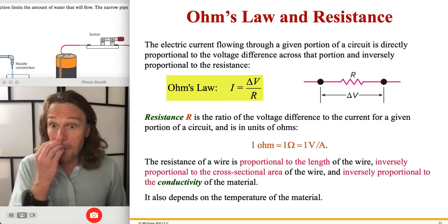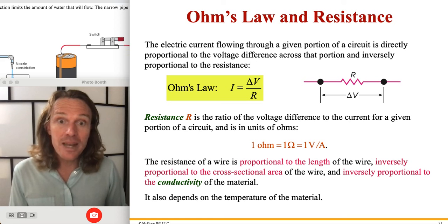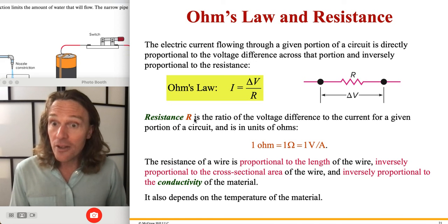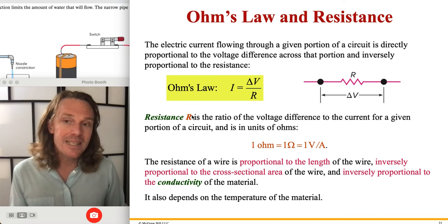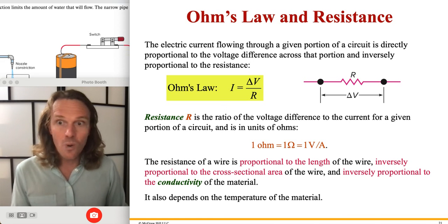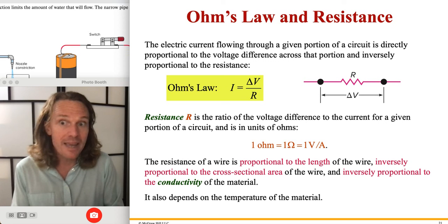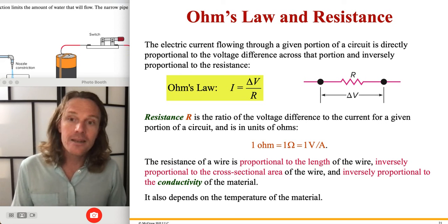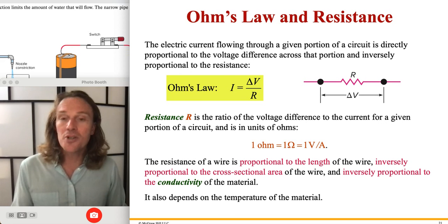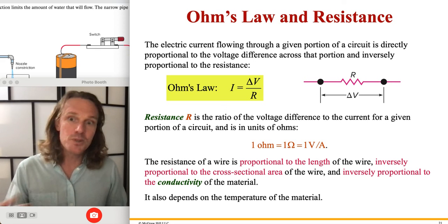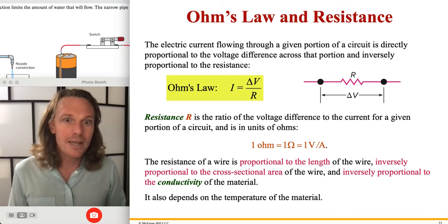And the amount that's being released is dependent on how big the value of resistance is. So the resistance is a sort of material quantity. It refers to the actual resistor itself and how it was made and what it's made out of, okay? The actual property of the materials is called resistivity, and you can look it up for different materials. And then the resistance comes from the geometry of how the resistor was made.